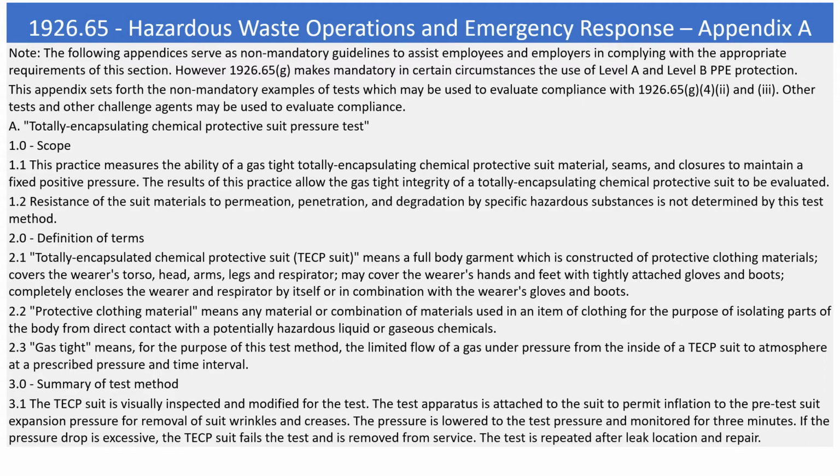2.0 Definition of terms. 2.1 Totally encapsulated chemical protective suit, TECP suit, means a full body garment which is constructed of protective clothing materials, covers the wearer's torso, head, arms, legs, and respirator, may cover the wearer's hands and feet with tightly attached gloves and boots, completely encloses the wearer and respirator by itself or in combination with the wearer's gloves and boots. 2.2 Protective clothing material means any material or combination of materials used in an item of clothing for the purpose of isolating parts of the body from direct contact with potentially hazardous liquid or gaseous chemicals. 2.3 Gas-tight means, for the purpose of this test method, the limited flow of a gas under pressure from the inside of a TECP suit to atmosphere at a prescribed pressure and time interval.